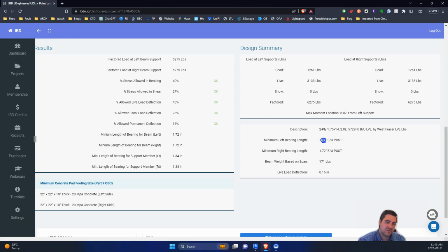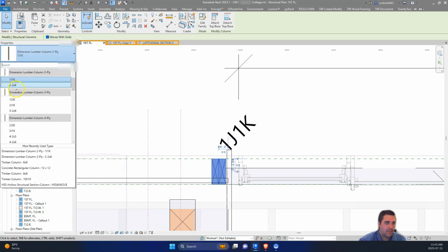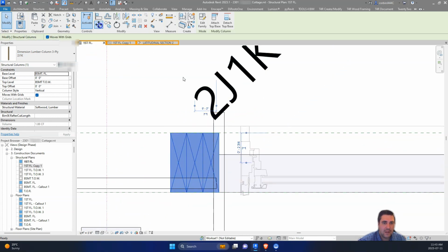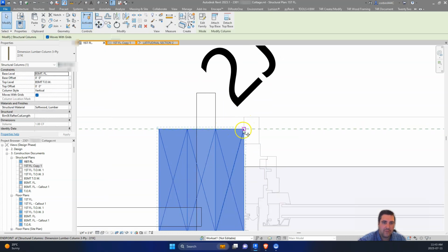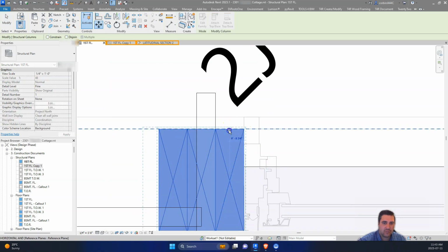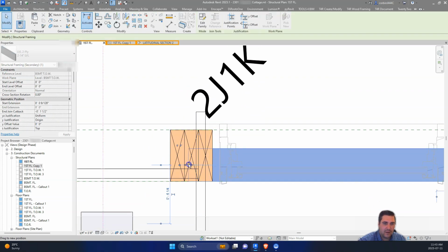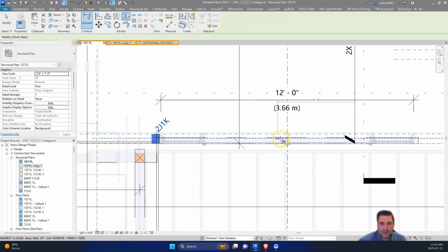And then when we move this over to the window, generally it's 3/4 of an inch, but it doesn't need to be exactly. And then I don't always do this, but theoretically you can move this beam so it meets up with the J. Yeah. And then I'll just grab both of these here, and I can mirror this over to the other side. 2J, 1K, and then you can again stretch this over. And so we'd want to add those posts everywhere.